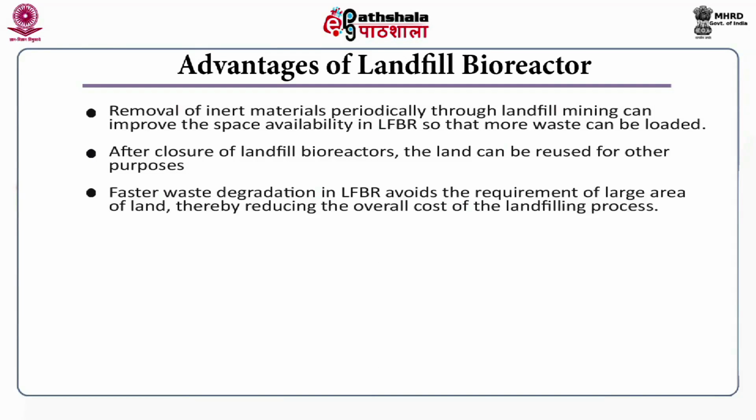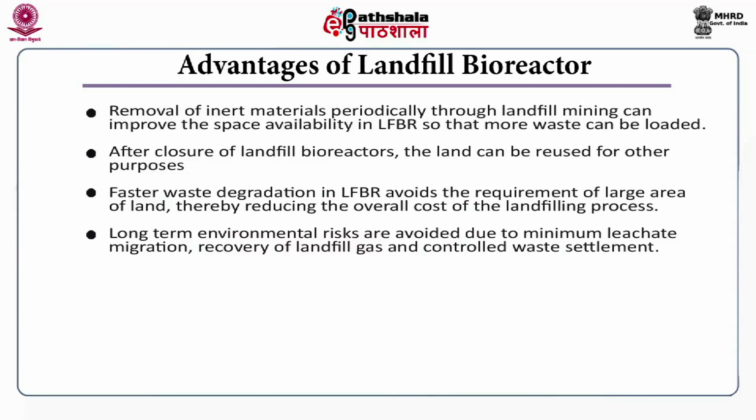Faster waste degradation is attained inside the landfill bioreactor, and hence it avoids the requirement of a large area of land. Thereby the cost is also reduced when you use a landfill bioreactor. Long term environmental risks are avoided due to minimum leachate migration, recovery of landfill gas and controlled waste settlement.